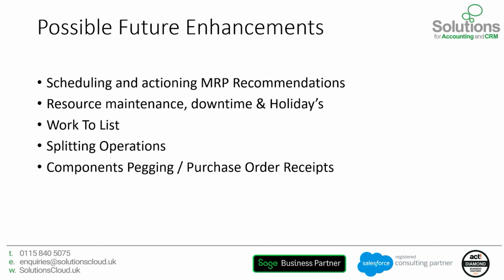What you may want to do from a production planning point of view is split that out to say, yes, we do have 100 parts that need drilling, but we would like to split those so we have 50 parts going on drill 1 and 50 parts going on drill 2, so we can halve the time that the drilling operation is going to take.